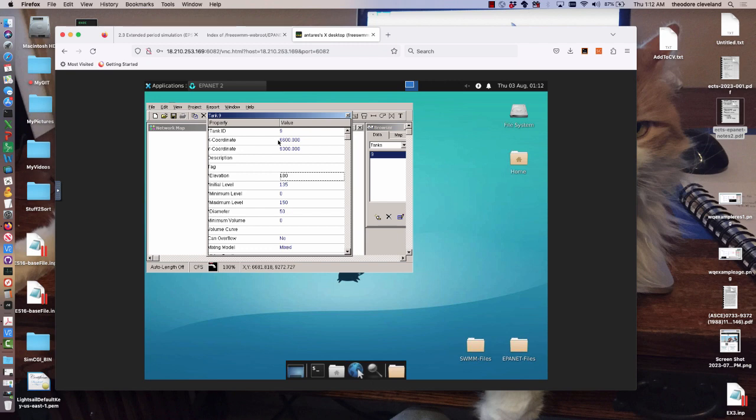Okay, returning to our example, here's our tank, and you'll see this section volume curve. There's nothing there, so all the tank information is contained in these few lines. So it's a cylindrical tank with a 50-foot diameter.